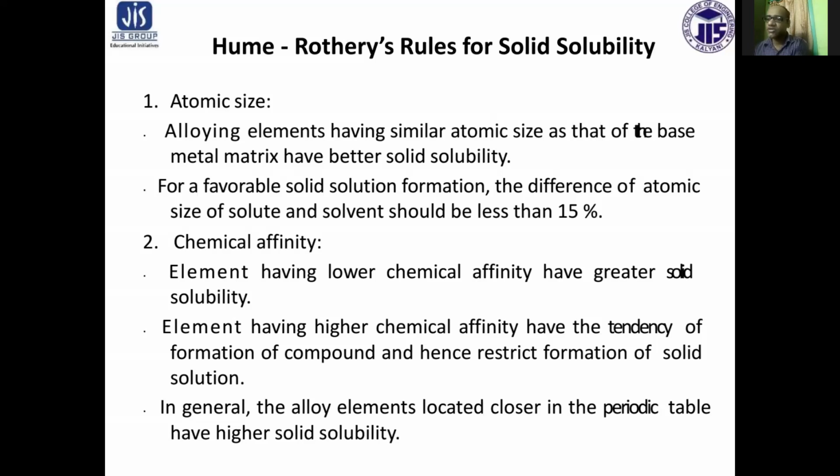They are as follows. First of all, the atomic size factor. Alloying elements having similar atomic size to that of the base metal matrix have better solid solubility. For a favorable solid solution formation, the difference of atomic size of solute and solvent should be less than 15%.